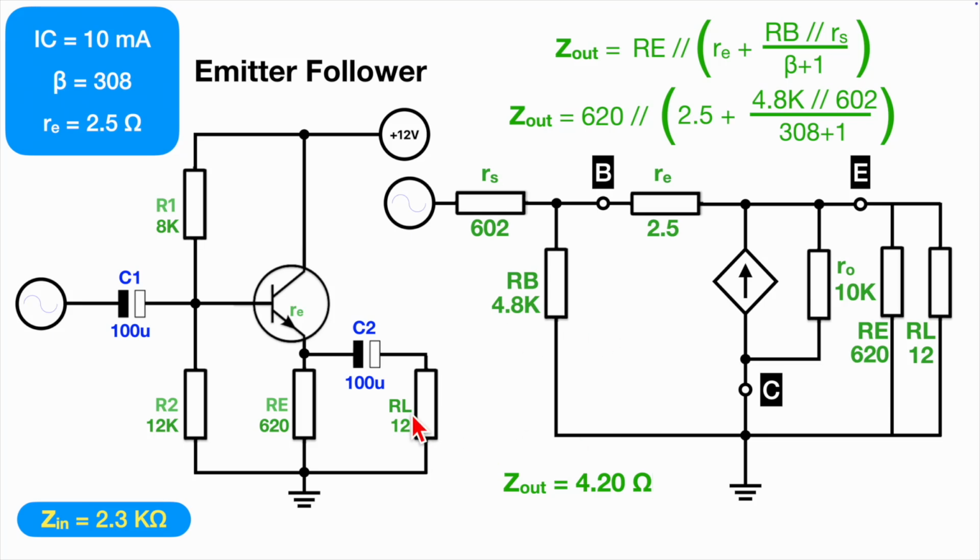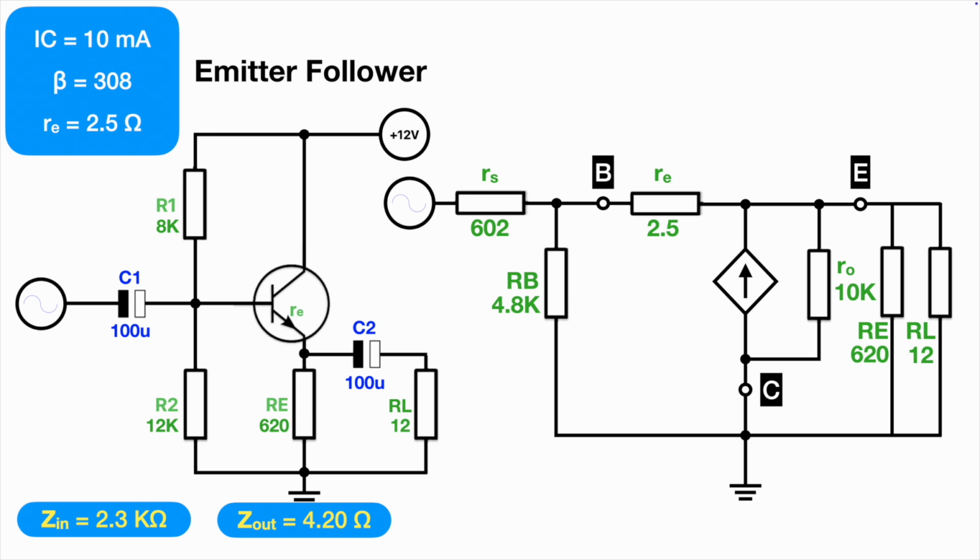So that's absolutely fine for me to put my 12 ohm speaker on that. Fantastic, and that's what we would expect from this kind of design. And finally, just to calculate the voltage gain, the way that you do this with a common collector, an emitter follower amplifier, is essentially RE paralleled with RL, divided by R sub E plus the parallel of RE and RL, okay?